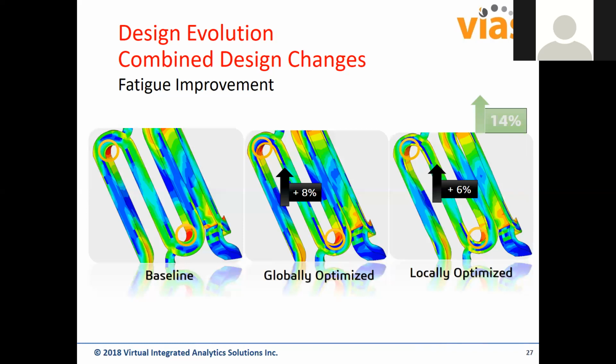And we further took that into Tosca, and we can apply any manufacturing constraints, that it should be no thinner than this number, or the transition between two surfaces. You could also put a restriction on that to allow for manufacturing. And once we complete our Tosca local optimization, we have an overall improvement of 14%. And in some cases, 14% could be a defining factor for that product. And if it means 14% fewer surgeries in a patient's life, I think anybody would want that.